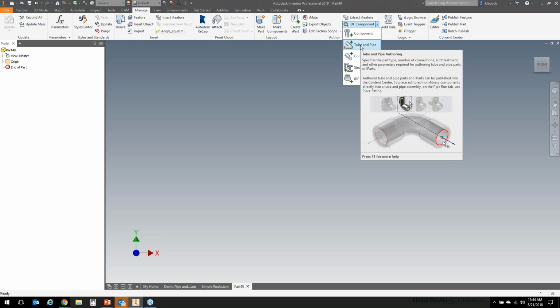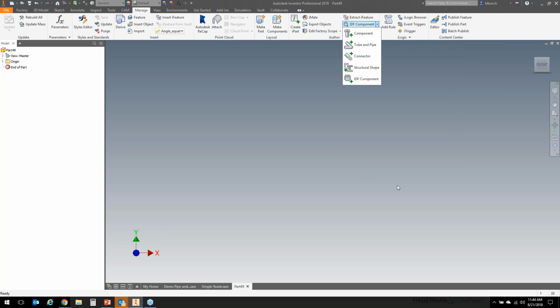Typically, you probably download something maybe from McMaster-Carr and begin with that, going through the publish options. But it's not a terribly complicated process. It's just a little bit of time. And let's see, can that hose length be calculated in a drawing on bill of materials? I believe it is a parameter, so I do believe you could export that to a property and then import that into your parts list or bill of material.